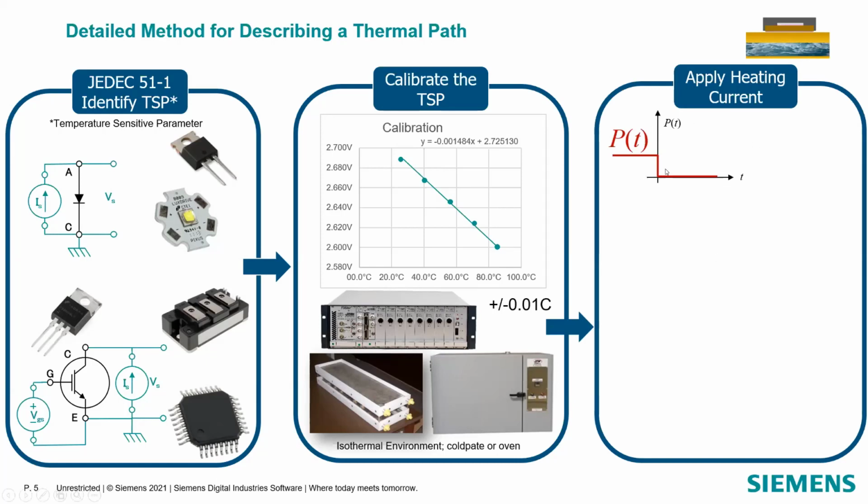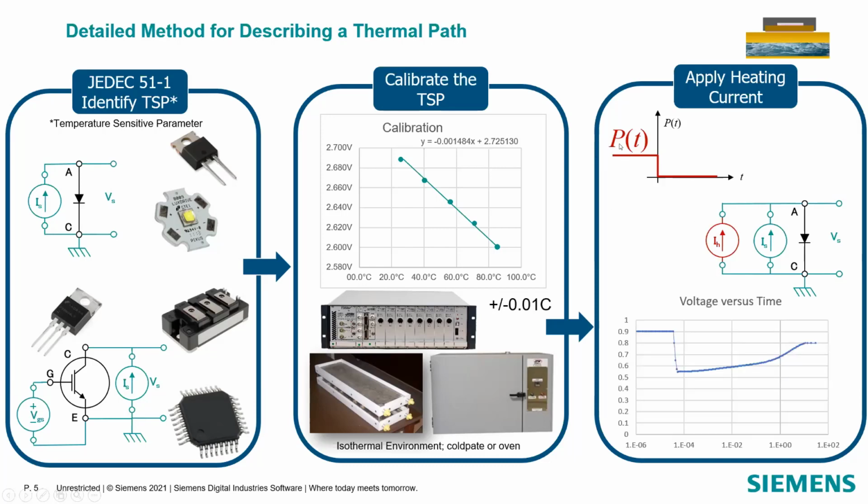To understand the Rth, so thermal resistance, and thermal capacitance features of the system, we need to use probing functions. Typically, it's a power step. So to establish it, we are using a heating current source most of the time, which can be turned on and off, creating the high and the low power. And when we go from high to low, the systems capture the corresponding voltage response. With a negative TSP, you actually can capture a positive and increasing voltage curve, which is temperature related.